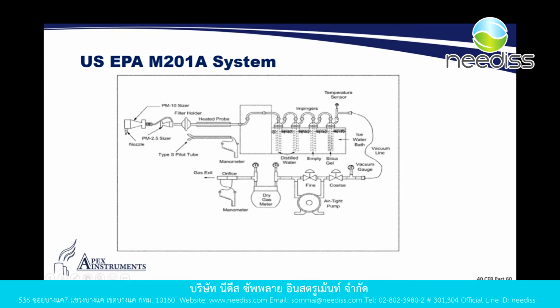A point while I'm talking about this, just a little stack tester tip from years and years of experience. Many of our clients and myself, we put a small amount of cotton wool right here in the last impinger outlet, right in the glassware. And all that does is act as a plug, a safety net,